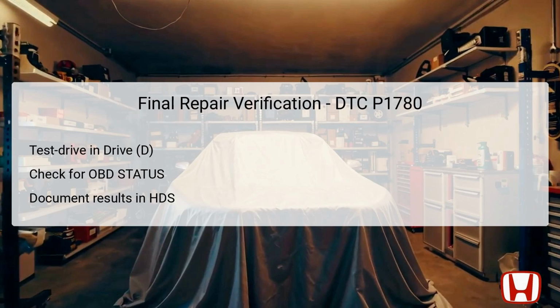Start by test driving the vehicle again with the shift lever in drive, D, allowing the transmission to go through all 5 gears as before. During the drive, closely monitor the vehicle's performance to see if it shifts smoothly and correctly without any erratic behavior. Utilize the Honda Diagnostic System, HDS, to check the OBD status for DTC P1780. This step will indicate whether the fault has been cleared and if the system is functioning as intended.